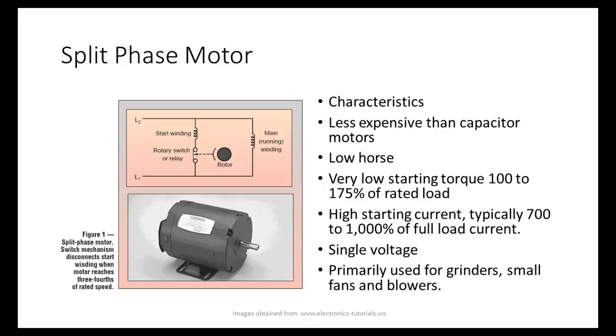Inductors can create phase shifts too. So this is what we call a split phase motor. It's using an inductor to create phase shift. It's less expensive than capacitor motors, very low horsepower, very low starting torque, high starting current, single voltage, primarily used for grinders, small fans, and blowers.